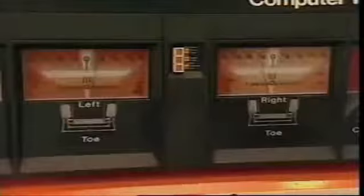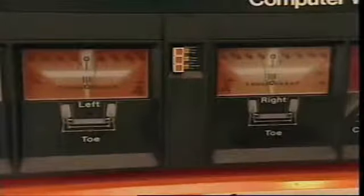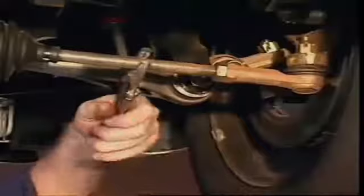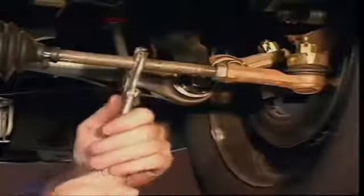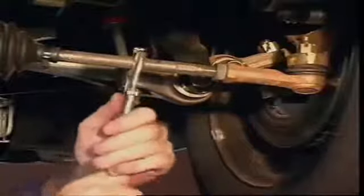Each steering system makes provision for adjustment of the linkage to achieve the manufacturer's recommended toe setting. The track rods or tie rod ends are threaded to provide for their lengthening or shortening.